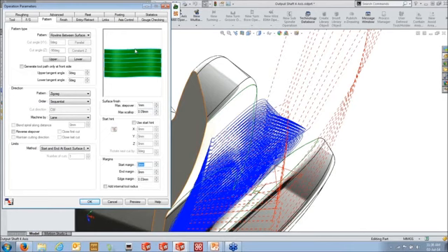So if I want to pull the toolpath away from this particular edge at the top here, I would go in and say, maybe give it an edge margin. I could set maybe a millimeter up here, and then it's going to be a millimeter from either edge, the top edge here and the bottom edge. Or if I wanted to say, hey, I just want to generate it away from the top edge here, maybe it's causing some weird looping, just put in a millimeter right here, and it will control it and pull that tool away from the actual edge there.